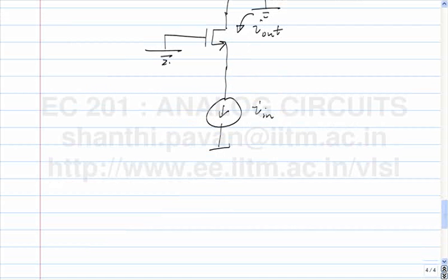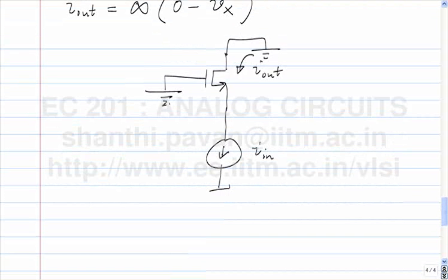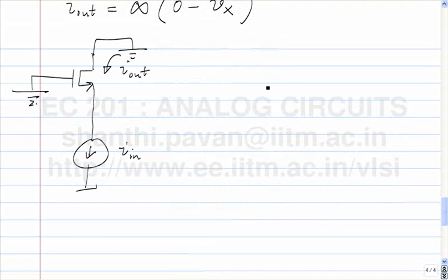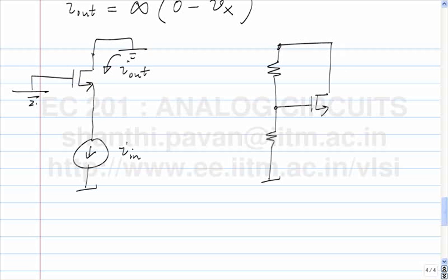Okay. This is the incremental circuit, so we need to do the bias. Can somebody help me with the bias? RA, RB, somebody says. We need to bias the transistor in saturation. So this is VDD. The drain is grounded. This is RA. This is RB. The gate must be grounded. So what should I do?